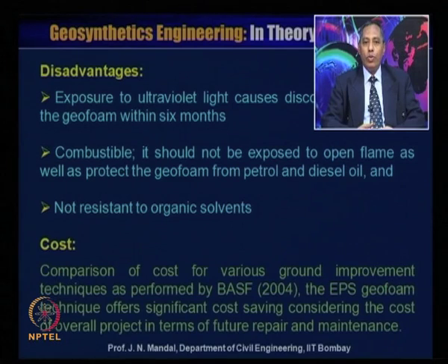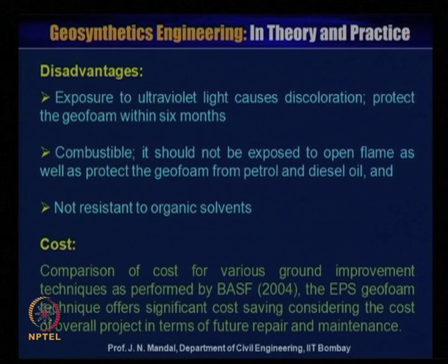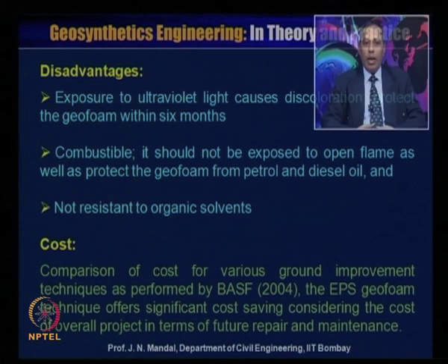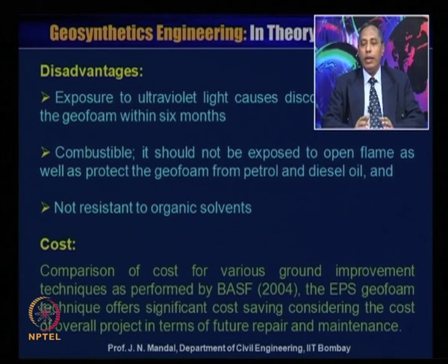Exposure to ultraviolet light causes discoloration, so protect the Geofoam within 6 months. It is combustible; it should not be exposed to open flame, and Geofoam must be protected from petrol, diesel oil, and has no resistance to organic solvents. So one has to take care in the use of Geofoam material.